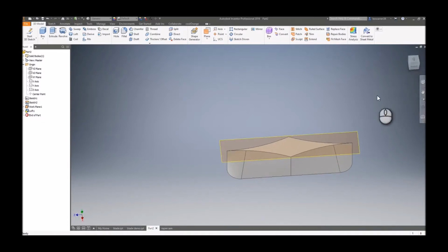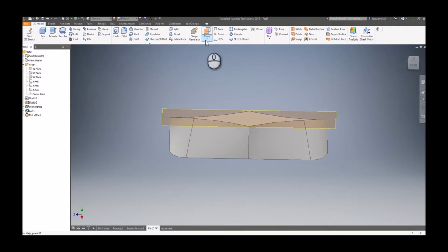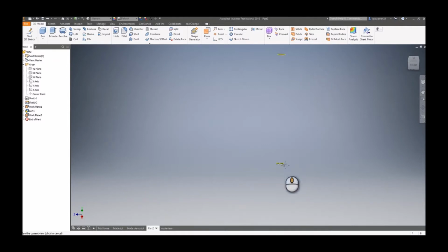You can also use different profiles, lenticular, or you've got fullers in there where it curves in on itself. But for now, the main focus is making the actual blade length. So we're now going to make another plane, XZ, and let's just say for argument's sake we can make it 400. This will then be a 40cm blade, so it's going to be relatively short.